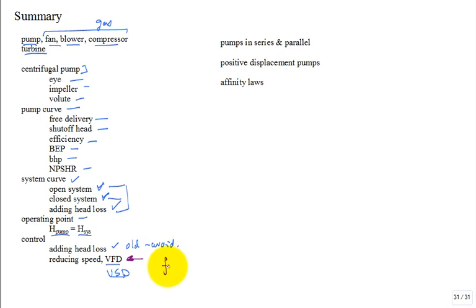Oh, frequency. Frequency of the electric current and the voltage, the EMF of the electric current that's fed to the motor. You just can't leave it at 110 volt and just toggle it down in frequency. It'll burn out the motor. You've got to bring down the voltage as well as the frequency in the right proportion, and then the motor's happy. The electric motor's happy.